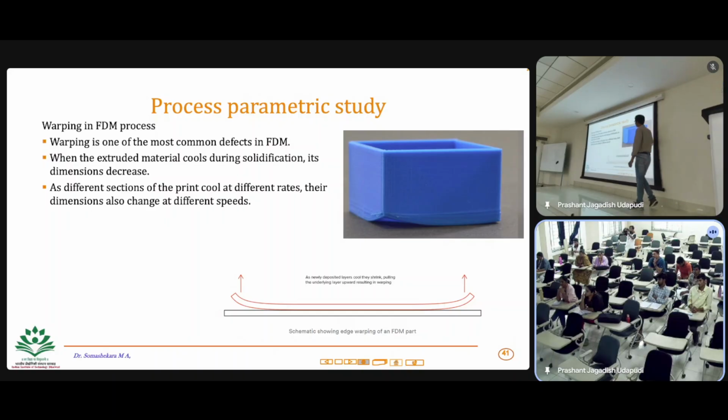There you need to change the bed temperature, and sometimes also if you don't give enough temperature for fusing, right? That also will result in warpage, because you might not have given enough temperature for it to fuse the material. If you don't fuse it or liquefy it, it will not stick to the bed, right? Because of which eventually it will come away. You need to have enough temperature, enough in terms of melting temperature, so that the material will go and stick to the bottom.